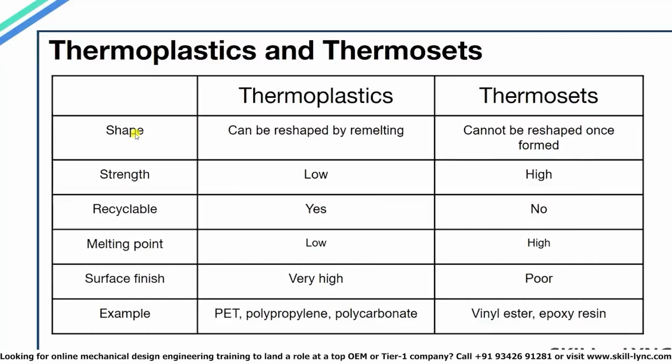All plastics can be divided into two major types, thermoplastic and thermoset. The primary difference that you need to know between these two types of plastics is that thermoplastics can be remelted back into a liquid repeatedly, whereas thermosets once shaped cannot be remelted. This happens because when thermosets are heated, the polymer chains are attached together with a process called cross-linking, which gives it a permanent 3D shape and makes it more resistant to melting. But since thermoplastics do not form these cross-links, they can be easily melted.